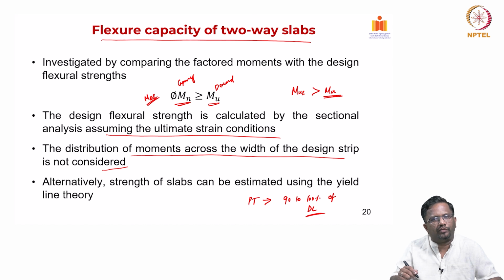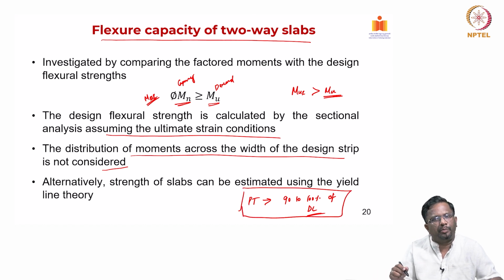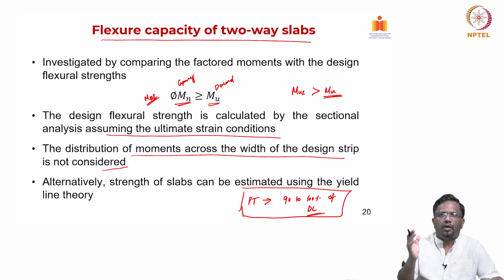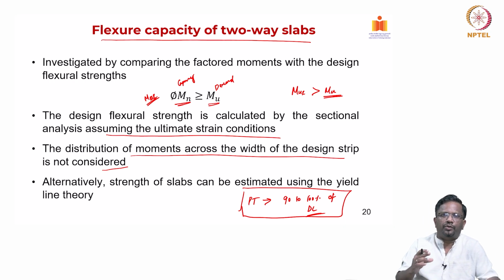That is the self weight of the slab. So, this is a typical layout with which we find the PT cable, right. But for that we are doing all the analysis. If for the ultimate condition this PT cable is also acting as reinforcement for ultimate strength, and it is not enough, then we put additional non-pre-stressed or TMT rebars to make up for the extra capacity, right.